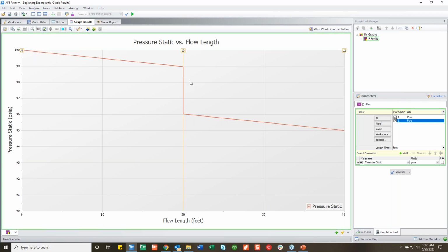So if I turn on my junction, J3 is my orifice here, that's where you see that large pressure drop. And then we've got pressure drop from friction through the rest of the system. And this orifice is a major player in determining the flow rate, because if I have more pressure drop from this orifice, I will have a lower flow rate, more resistance in the system. I will also have a shallower slope here so that there's less frictional losses because there's a smaller velocity. So just some theory there.